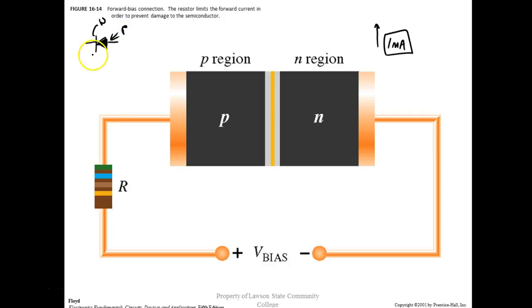So I can literally take an ohm meter and set it on the diode scale. And I can come up here and I can put that across there, and it's going to measure about 0.7 volts if it's good. If it don't measure about 0.7 volts, it usually means it's bad. So our meters have what we call a diode scale. Used to, you couldn't check them with a digital multimeter because they didn't put out enough current or voltage to break over the junction.